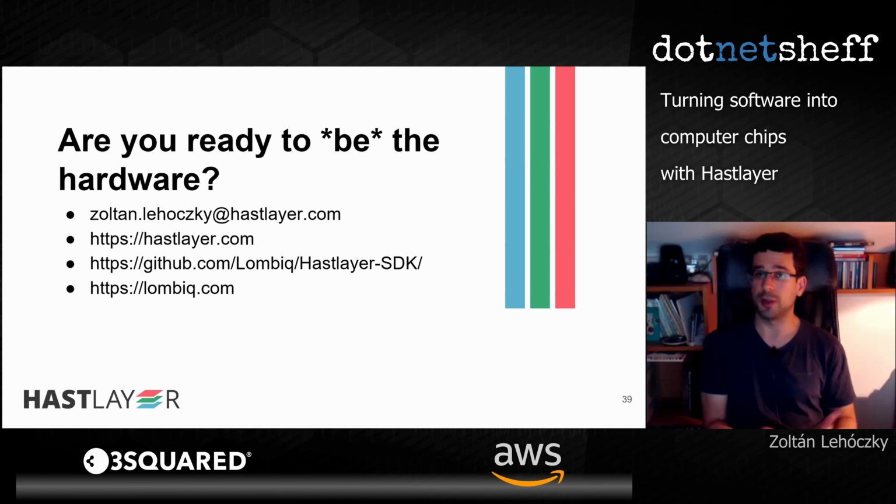FPGA developers do that a lot because the first step in debugging a hardware design is not to execute it on an FPGA, but even before that, to simulate it as hardware. So there are hardware simulators that you can use to look into what the signals do on the chip without actually using a chip for it.